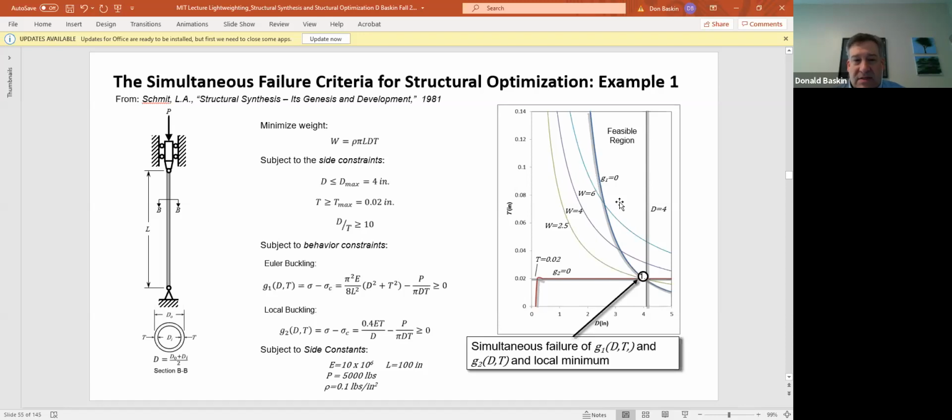But because it's hollow, you've got to worry about local buckling too. So your job as an engineer is, L's fixed. You can change the diameter, the outer diameter, and you can change the thickness T. So you have two design variables you can play with in order to find the lightest structural tube in this application that can support this load P, as in Paul.